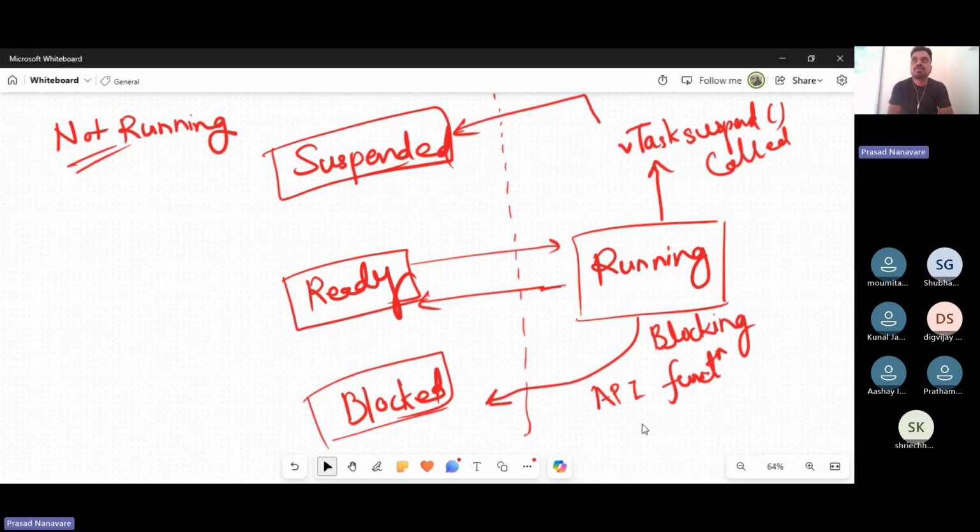Task would be first of all to detect the key press. Okay, that is the task, and I could set highest priority to that task. Okay, then initializing the LCD module, I could give maybe the lowest priority or mid priority to that, and then displaying whatever is pressed.